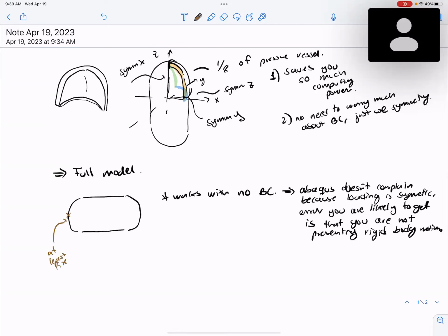And that actually reduces 3 of the rigid body motion modes. So it reduces the displacements. It doesn't reduce rotation. So this can still rotate freely. So if you want to prevent complete rigid body motions, you can fix extra points in special ways so that you still allow all deformations to happen, but you prevent rigid body motion.